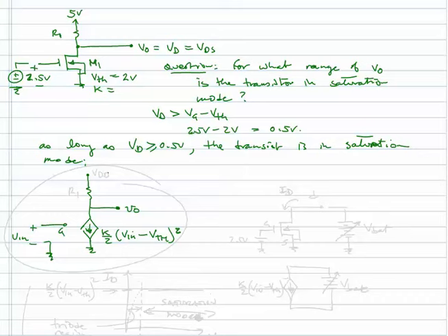Now, what if I detach this transistor out of this circuit for just a moment, just to show you how this transistor is behaving? Let's say I set the gate voltage to 2.5 volts. The source is grounded, and I take hold of the drain. And what I do is connect, say, a battery to this drain, a variable battery, V bat.